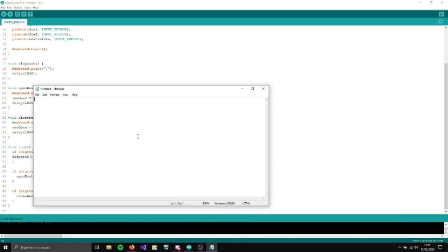I've got my yellow button here on the panel. I'm going to press that, and you can see it presses the open square bracket. Now it's just in its regular idle state, so I can press other buttons. It's gone back to the void loop. I can try and dispatch. The program won't let me, obviously, because it won't logically allow you to dispatch a train with restraints open. So now I'm going to press the yellow button again, and you can see it puts in a close square bracket. And I can keep on doing this. I can even hold it down, and it will just do open, close, and it will never do anything else. So this is great. This is the logic which you'd use for opening and closing restraints.